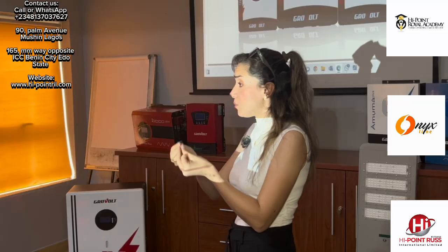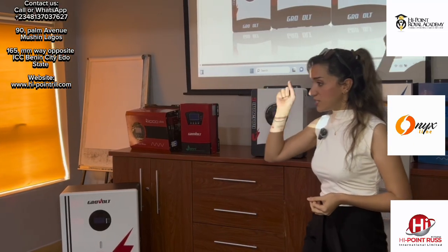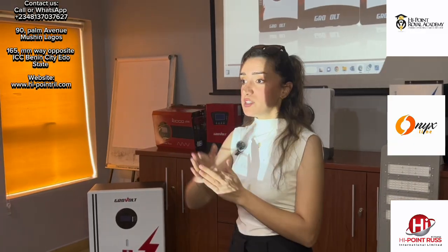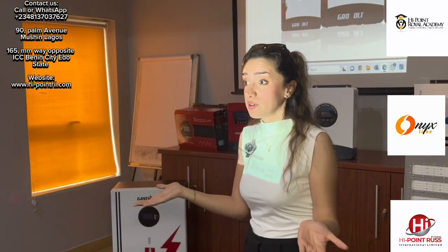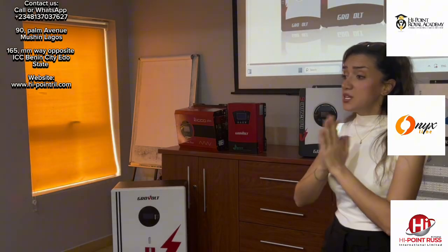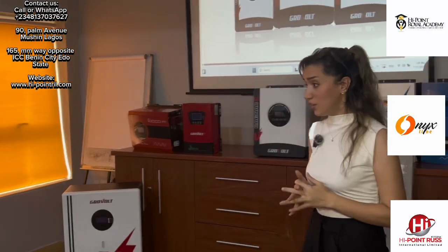That means also my cable is still in the small size, the thickness. If the distance is not much, 6 mm is enough, right? But please guys, I see a lot here in Nigeria, they use AC cable, not DC cable. It's a big difference. Okay?